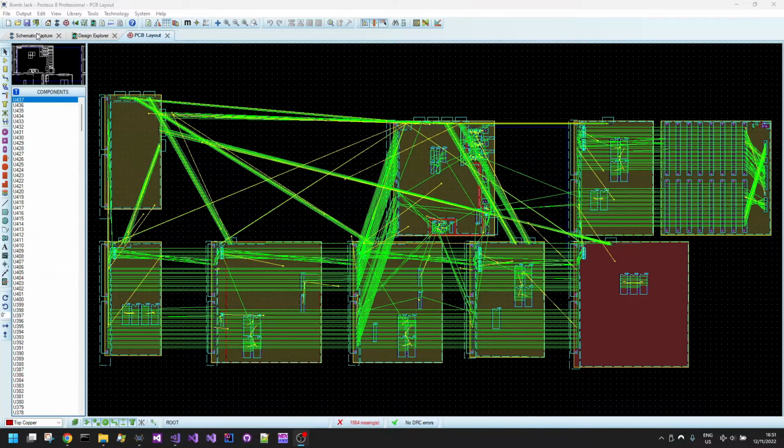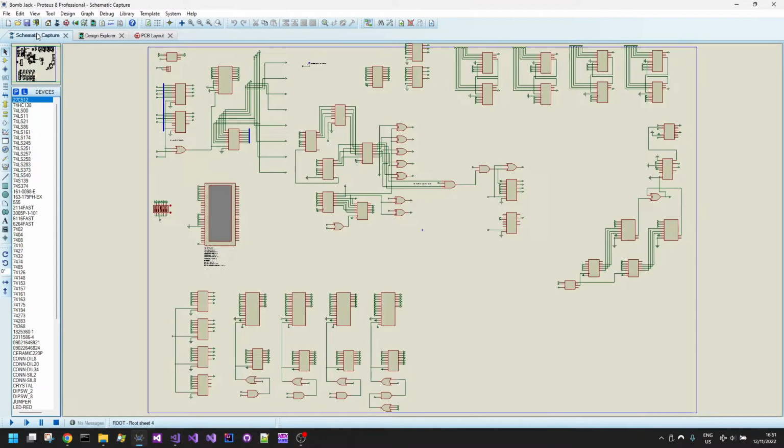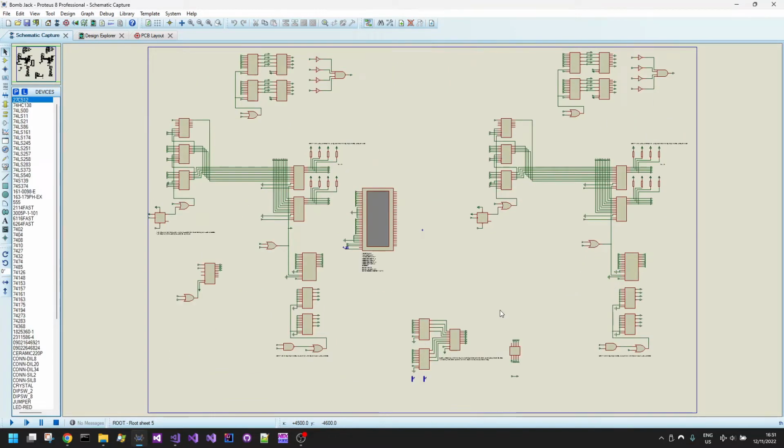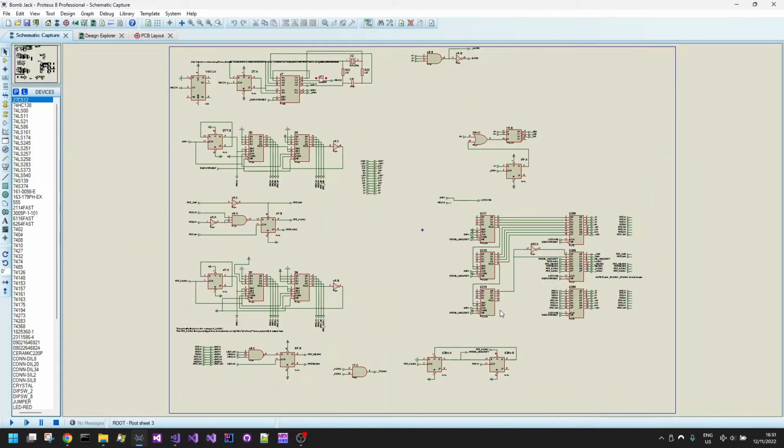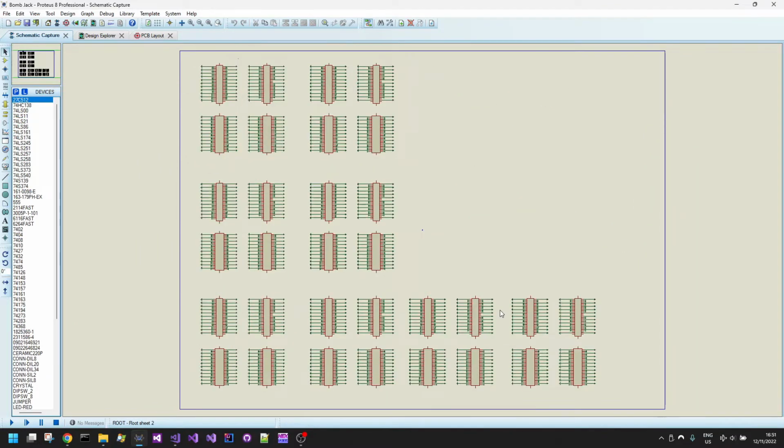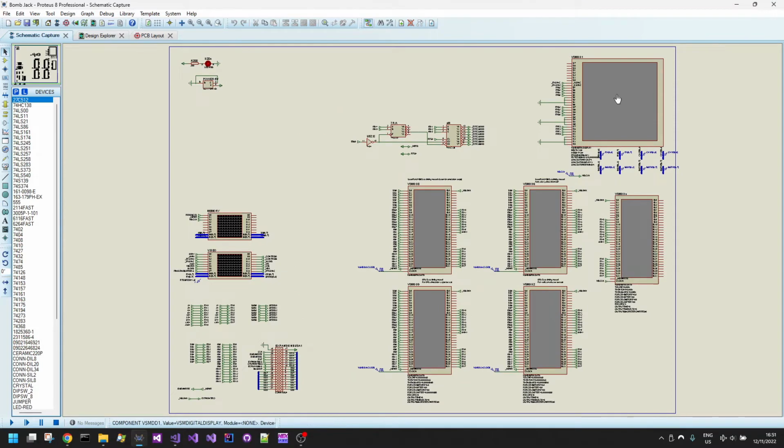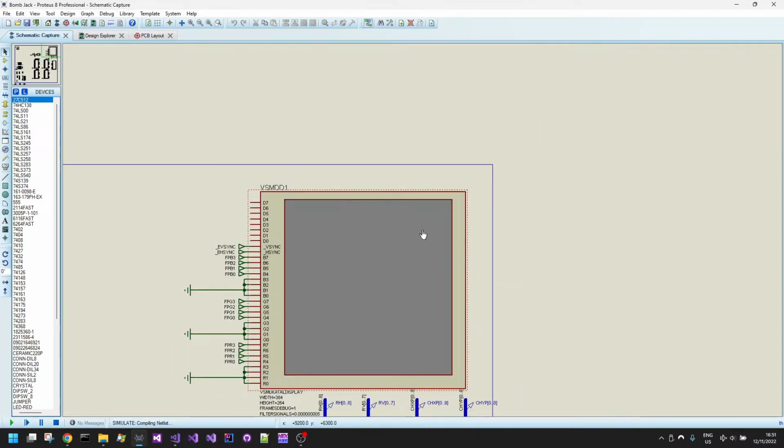This Proteus design tool is able to happily simulate very complex schematics, including all of the discrete TTL logic ICs that you can see here and here, for example. If I want to simulate this, however, and actually see visual results, it is quite slow because it's relatively complex to do a fully accurate TTL simulation.